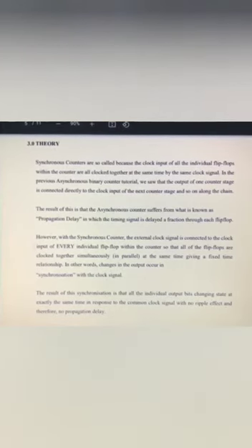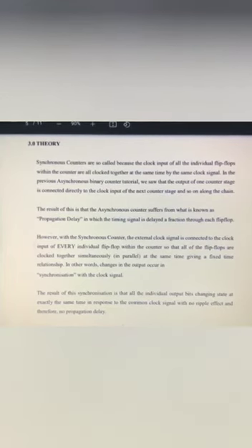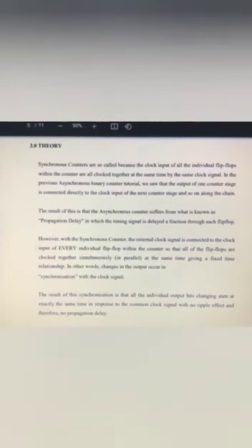However, with the synchronous counter, the external clock signal is connected to the clock input of every individual flip-flop within the counter so that all of the flip-flops are clocked together simultaneously, in parallel, at the same time, giving a fixed time relationship.